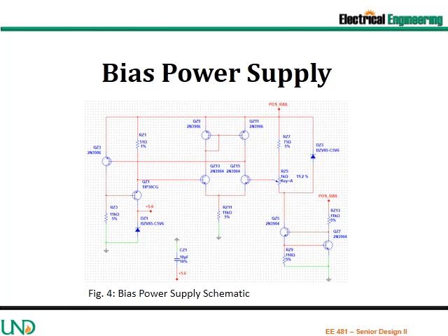The methodology is to provide a constant current source that is adjustable for testing and able to reject variations in power supply voltage. On the right is a current sink that provides biasing for the Zener diode DZ3 clamped to the positive rail. A potentiometer allows adjustment of the voltage desired across the current sensing resistor, RZ1. Both the set point and the current sensing resistor voltages are fed into the differential amplifier.